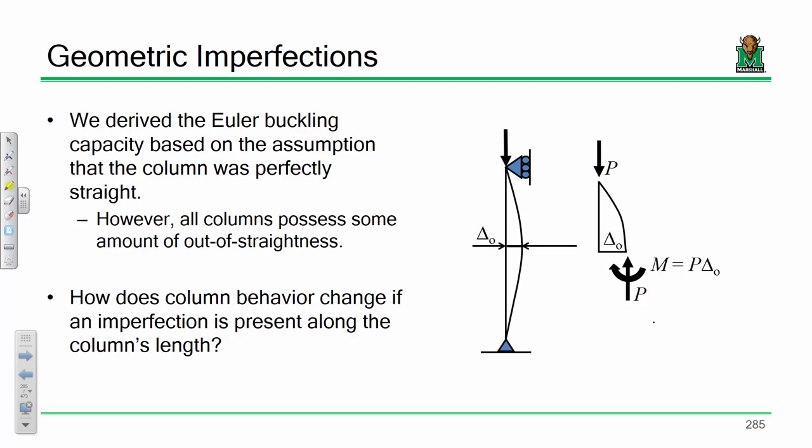That's a great question. The difference between the camber that you induce in a bridge versus the initial curvature that you get in a column is that the camber in a bridge is desired. You know that the beam is going to deflect downward some, so you're bending the beam up to get rid of that. But a column, you don't want that column to have a little bit of bow, because if you put people up here, whoo, that's bad. You don't want that to happen.